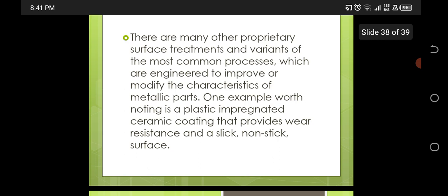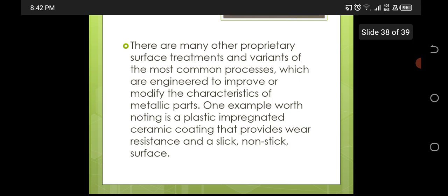This shows that both are thermal processes, and thermal processes are preferred because they increase the temperature of the target to a very small extent, meaning the temperature increase of the target material is very low as compared to galvanizing. So we prefer thermal spraying over galvanizing.